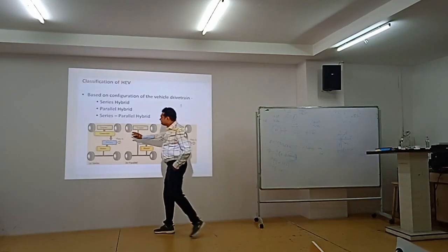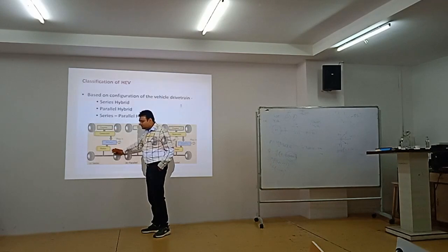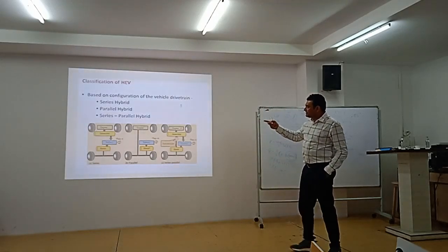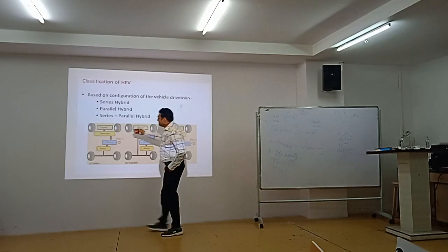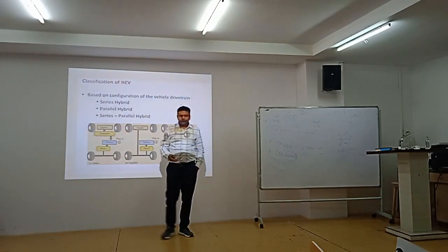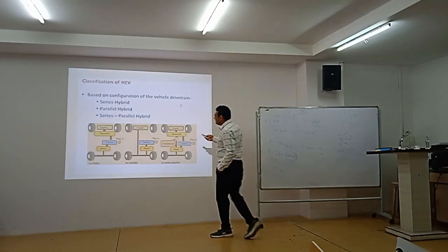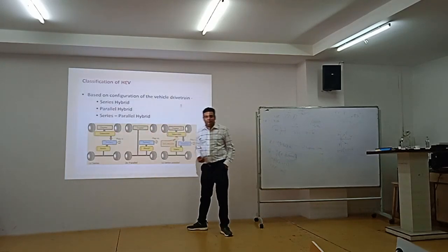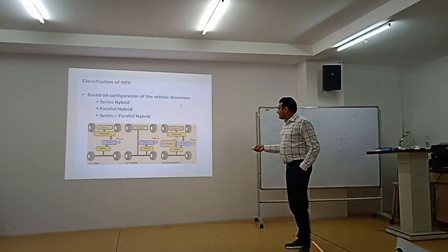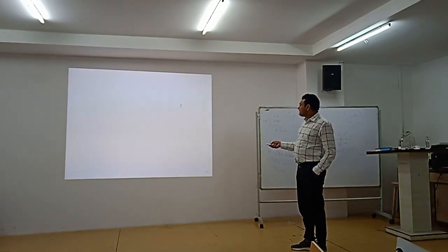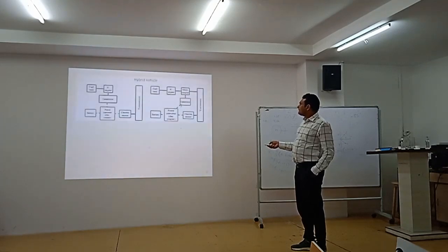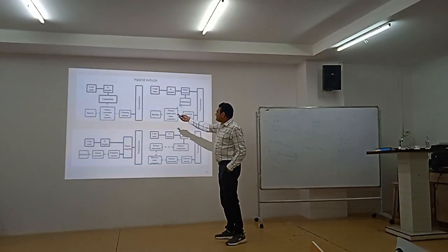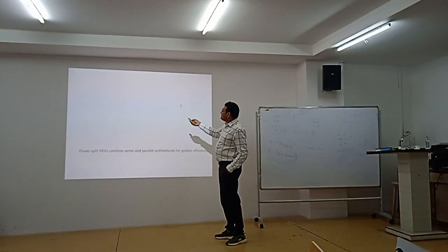You can see here, this is a series hybrid model where the wheel power transmission is continuously by generator, battery and motor. Whereas in case of parallel hybrid, the battery is separately connected, one via engine and one via motor. This is a good diagram. Series and parallel hybrid.